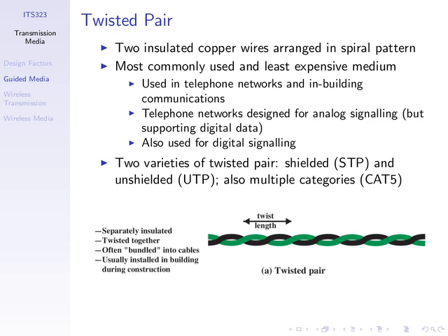such that the receiver will not be able to distinguish what it receives. When it receives a signal, it's a combination of the transmitted signal and noise. So if we're longer than 100 meters, the receiver will not be able to understand what the transmitted signal was. So usually there's some limit or recommended limit on the maximum length of your cabling. There are other reasons for this limit in Ethernet as well. So that's one example, and the most common transmission media used for wired communications, twisted pair.